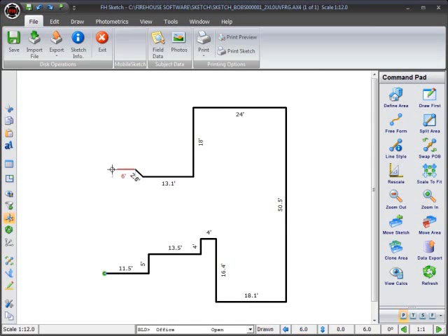I'll draw this line and anchor it in place. To draw the other side of the bay window, I'll enter 2 down and 2 left. When I do this, you'll notice alignment with the point of beginning, which is indicated by the red handle you see here. While creating the area, you'll notice many alignment indicators that aid you in drawing. I'll anchor the line and remove the redundant dimension by pressing spacebar.